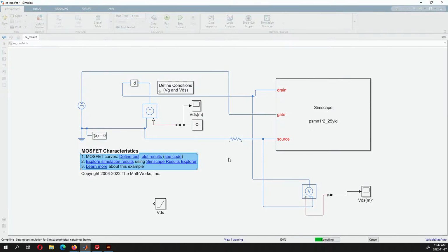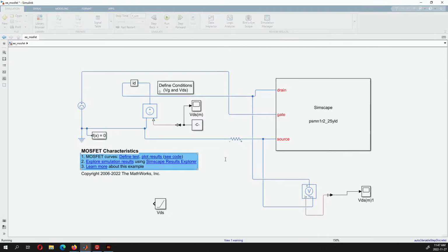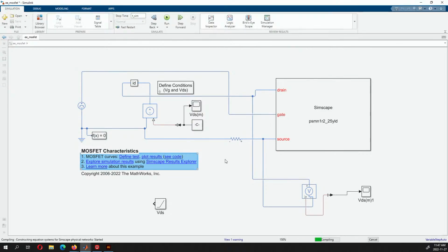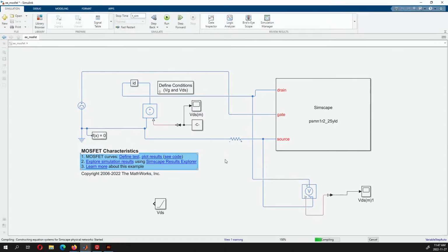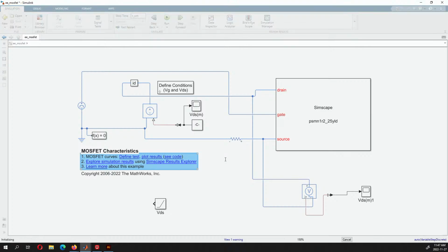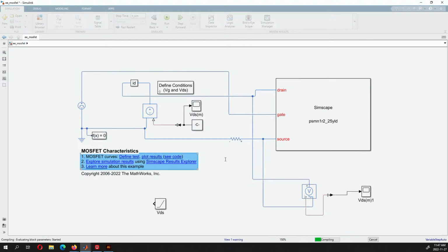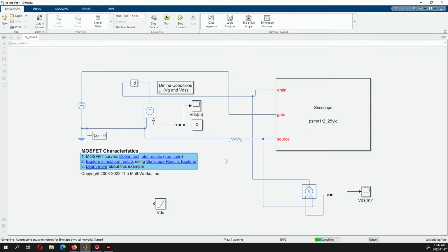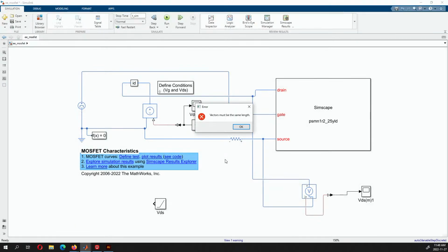And this is a way of basically saying that if I keep increasing the gate voltage, how much current can flow from the drain to the source. So this is not a basic video on how MOSFETs work. But in a simple sense, if you increase the gate voltage, the amount of current that can flow from drain to source will automatically increase till you reach a resistive value, or ohmic region, as they call it, which is basically you've pretty much turned on the MOSFET, and it's got the least amount of resistance. But before it turns on, it's not always a linear output.